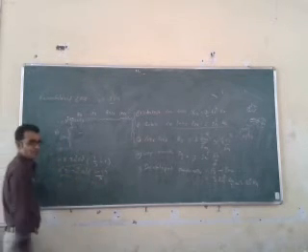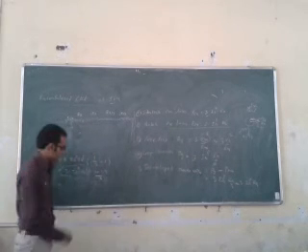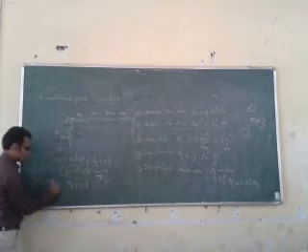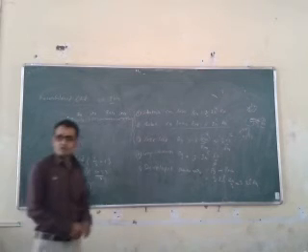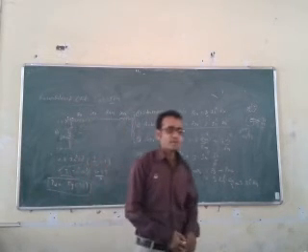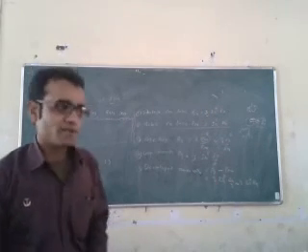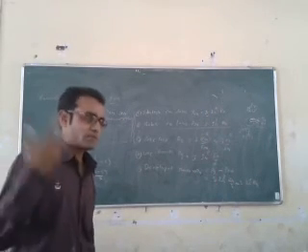It is again similar to this PG. It is equal to PG into (1 minus S). What is this? Developed power, the power actually developed inside the rotor, which depends on two parameters. One is the power transferred from the stator, and second, the actual slip of the machine.